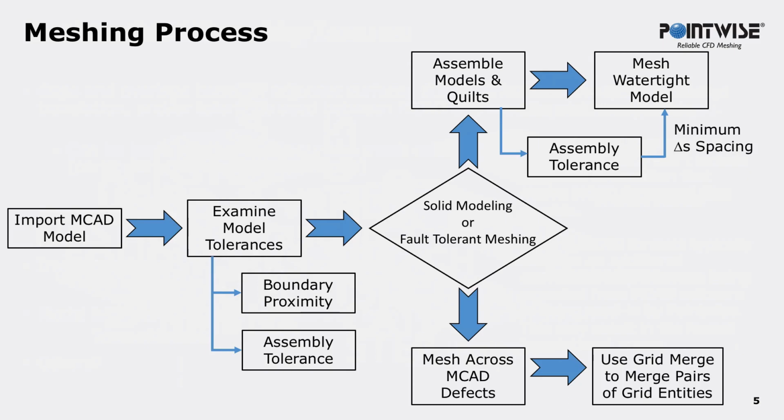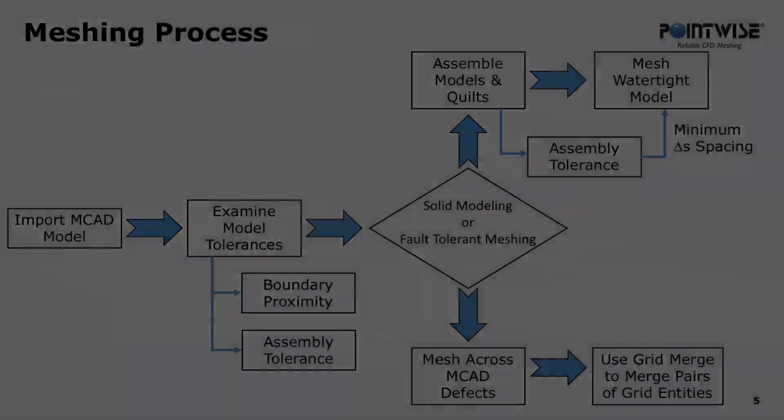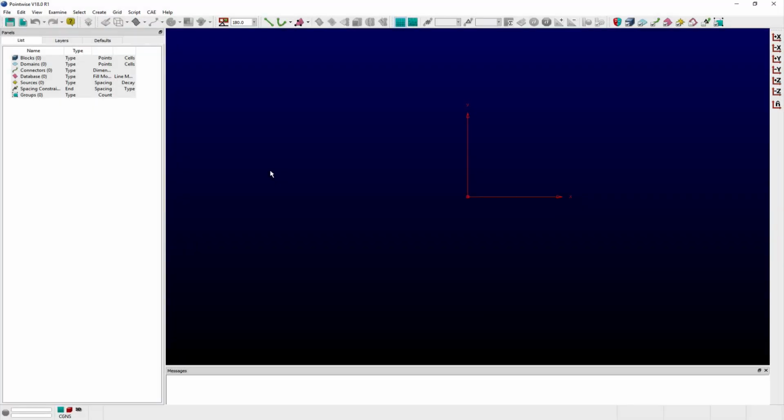Based on how extensive the geometry cleanup task may be after importing the geometry, and how often this model will be used for creating meshes, users should assess and determine which meshing approach, solid modeling or fault-tolerant meshing, to pursue. We'll delve into more details about both of these techniques shortly. Each approach has a set of strategies that we'll also cover. So let's begin with a demo and take a closer look at version 18's CAD import settings.